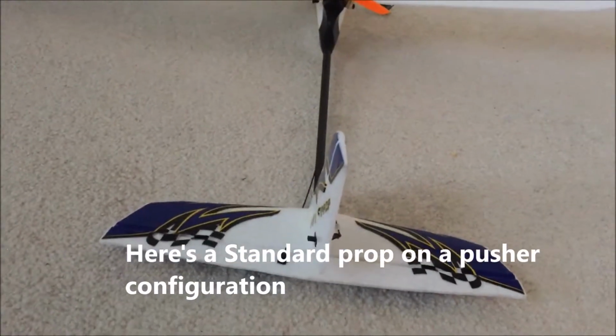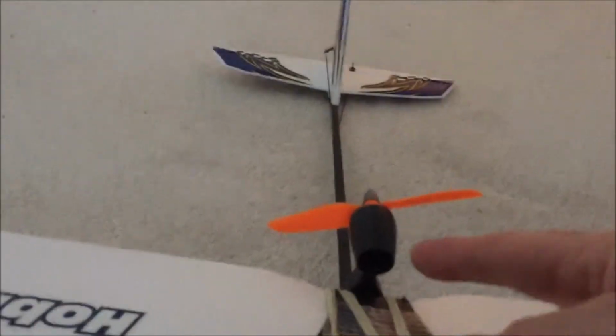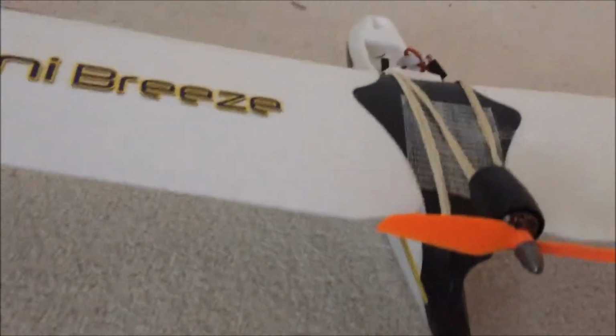This is an example of an RC plane in a pusher configuration where the brushless motor has been set up to rotate in a counterclockwise direction. So the brushless motor's in here and it rotates counterclockwise. From behind the propeller, that looks like a clockwise rotation direction, which means that we can use a standard propeller.